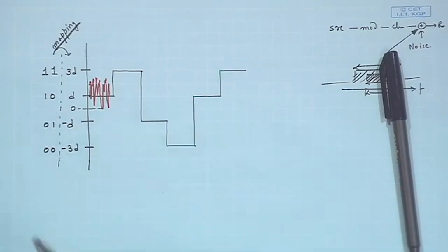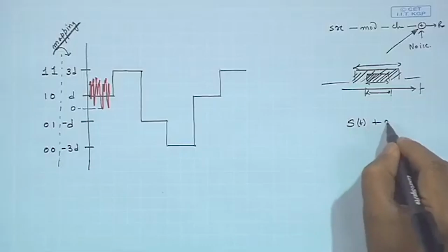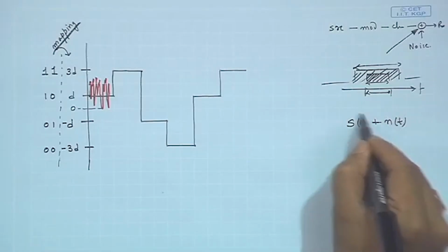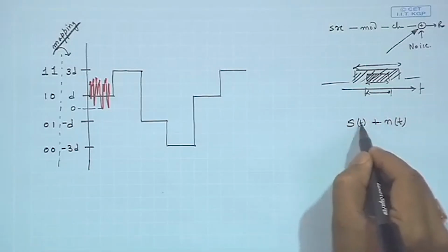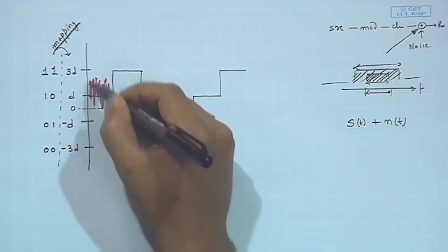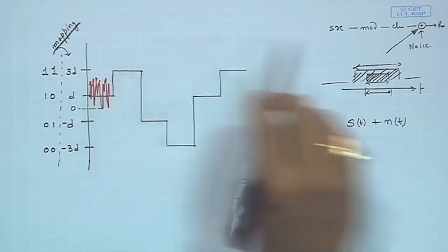Okay. So, getting back, additive white Gaussian noise could produce a time domain waveform which is like this, which is zero mean. We have always said that it is zero mean. That means, if I am sending a voltage, let us say D, then noise of zero mean gets added to that. So, for example, if I send S of t, I am going to add noise to it. It is zero mean. Therefore, the mean is that of the mean of S t, and if the mean is at level D, that means the combined signal will be around level D, right.